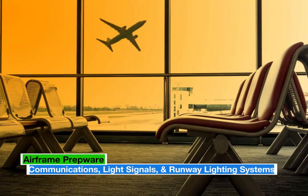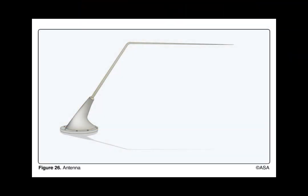Doublers are used when antennas are installed to reinstate the structural strength of the aircraft skin. Aircraft antenna must be grounded to the airframe. Refer to Figure 26. Where is the strongest signal for this antenna? Above the antenna.